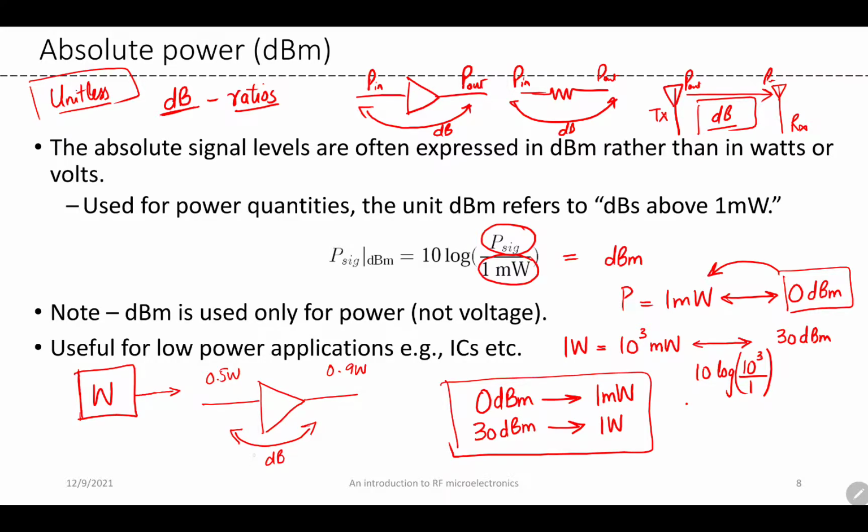And the amplifier has a ratio of, say, 3 dBs. Or to make it complicated, let's say we have a gain of 8 dBs, then we have to do a lot of conversion, because this is in the log scale. From this you'll have to calculate the ratio in the linear scale, then you'll have to apply it, right?